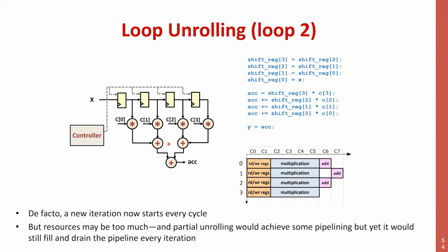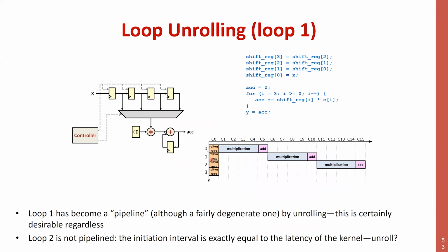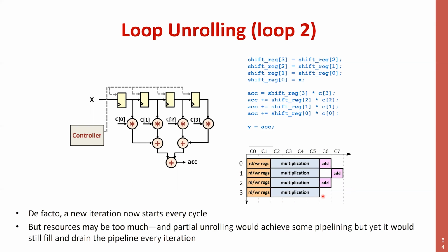This is a good result in terms of timing, because now you get the result much faster than you had here, and with a reasonable level of parallelism, but is maybe not what you want because it's extremely expensive, right? You are having 4 multipliers and 3 adders. You do achieve the parallelism at a relatively high cost.